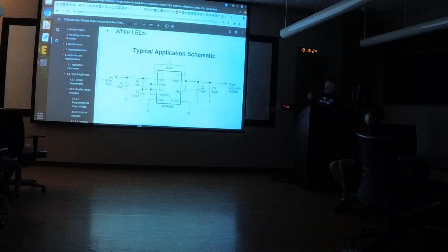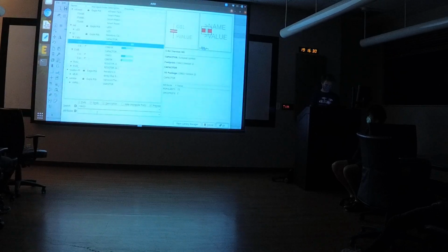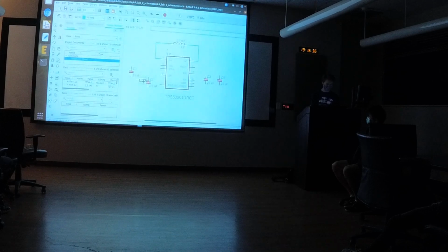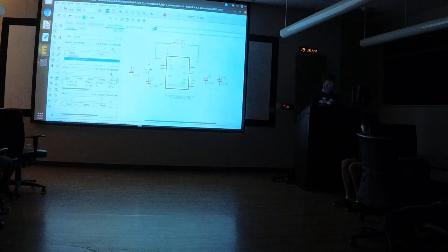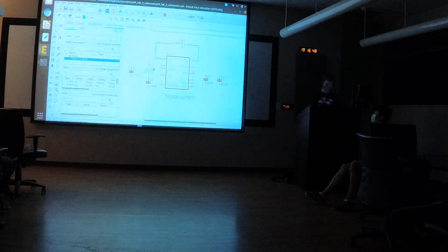Yeah. So then continuing, we see we have 1 resistor here, which is going to be 100 ohms. So we go add, and then wow, check it out. We're going to type in 0603. I'm going to use the European symbols, and again, that's just the way I do. Then we have to right click to rotate it, because obviously. Then we put it here, and we check the value. It's 100 ohms. So we type in value. We put the cross in a nice place here. So we just type in 100.